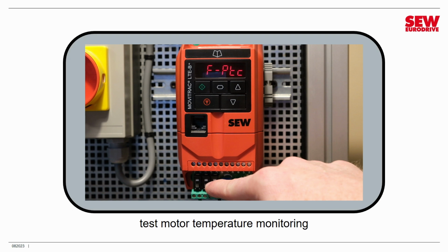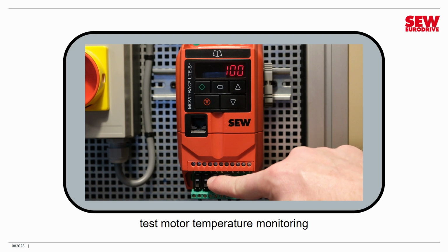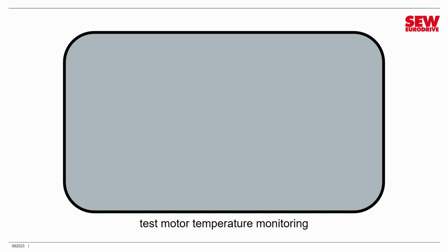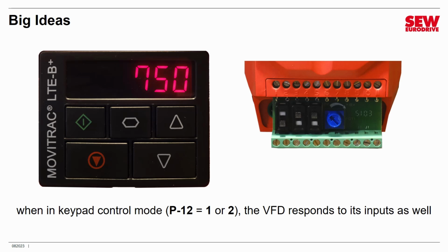I'll turn the switch on again to simulate cooling off, and I'll restart the drive. I'll trip it again, and I'll restart it by turning DI1 off and then on. Exactly the same behaviors as with a conventional external sensor, but a dedicated error message. All right, now let's move on to another topic associated with terminal control mode, and that is terminal control in keypad mode. You may not be aware of this, but when you're in keypad control mode, in other words, parameter 12 is set to either 1 or 2, the VFD actually does monitor its inputs, and it is controllable by the inputs.